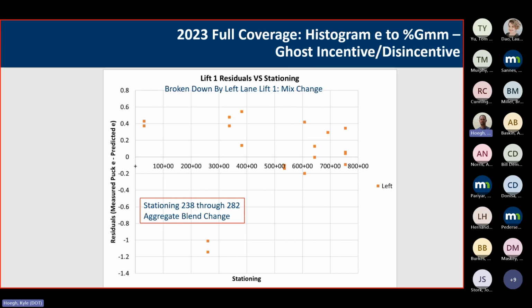I just wanted to mention quickly that the AASHTO spec we showed earlier is working well to track the dielectric properties of the mix. It's really critical for us to be able to non-destructively identify if there's a change dielectrically. Typically there isn't, but this is an example where a blend change did change our dielectric properties, and that's something we need to track, especially if we're going to use this technology for acceptance. And the e-ticketing, I'm excited about that too, because then we'll know exactly where that mix is going on the project.